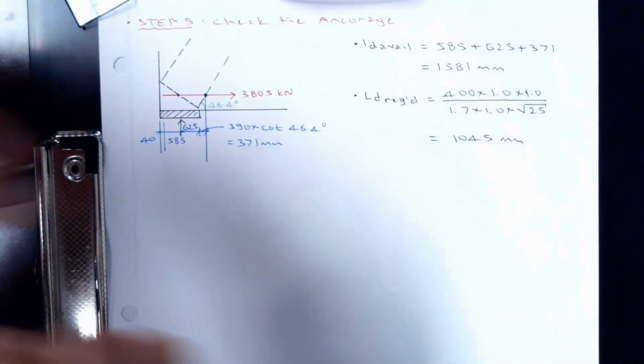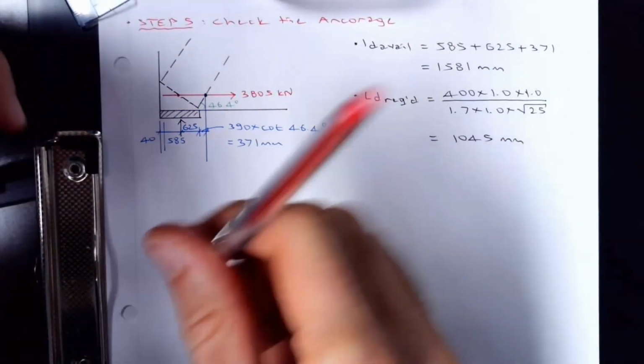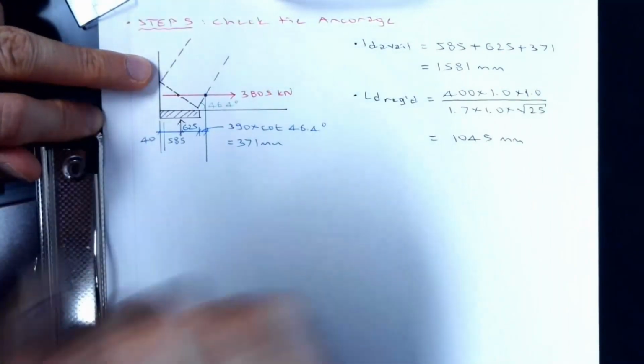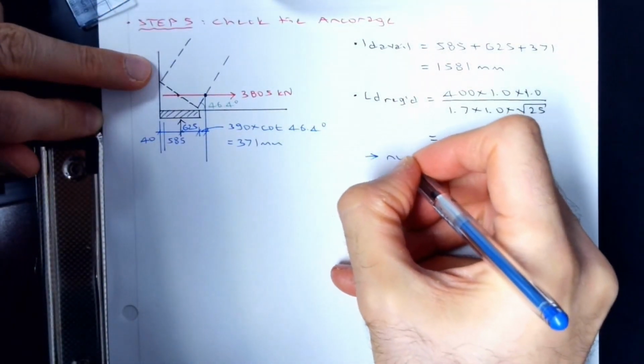It looks super tight. If you look at the figure, it looks like it's going to need it, but no. Straight bars would be fine. No hook needed. Just cut it straight. It's going to work because the strut is such a wide strut. You are checking it at this point, which is pretty good. No problem. No hook needed.